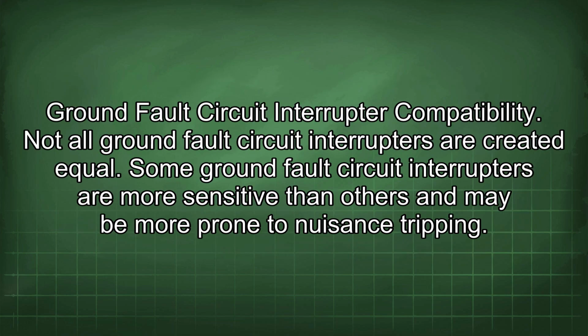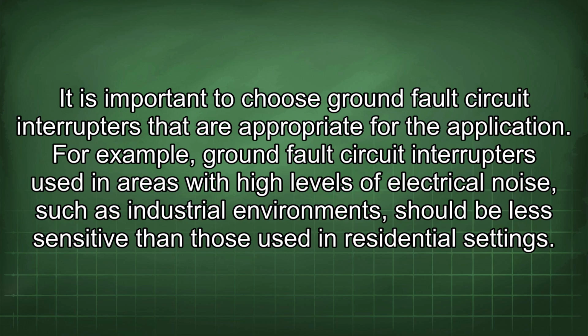Ground fault circuit interrupter compatibility. Not all ground fault circuit interrupters are created equal. Some are more sensitive than others and may be more prone to nuisance tripping. It is important to choose ground fault circuit interrupters that are appropriate for the application. For example, those used in areas with high levels of electrical noise, such as industrial environments, should be less sensitive than those used in residential settings.